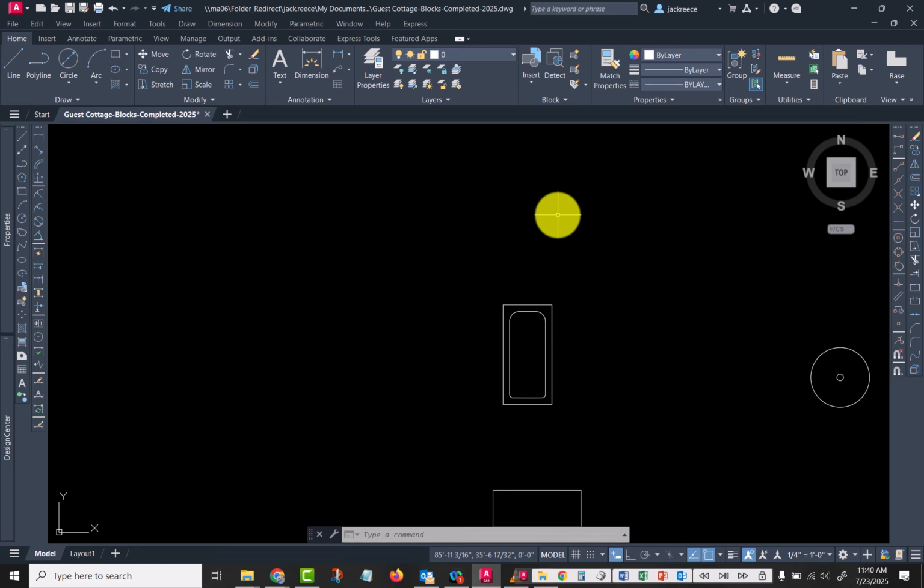So in this exercise, we're going to create the blocks in our drawing file, and then they are saved within that drawing file in a block library, even though they're not visible as part of the library. Now there is in the Design Center, which you've used to copy things from one drawing to another, a series of blocks that come installed with AutoCAD.